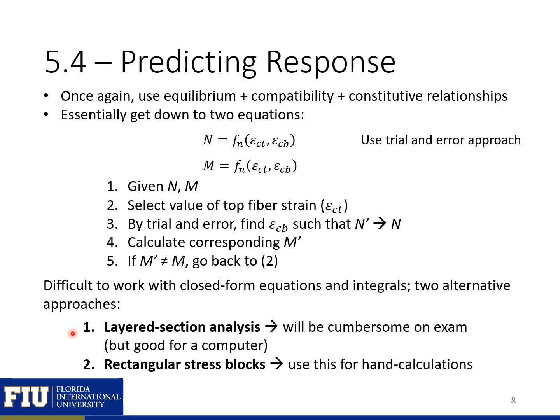So it's mainly used in computer programs, and you can actually develop your own Excel sheet with some macros to run a layered section analysis approach. The rectangular stress block approach laid out in Collins and Mitchell's textbook we'll go through. And this is another way that you can find the moment curvature response by hand, actually. So it's a simplified approach, and we'll go through this one as well.